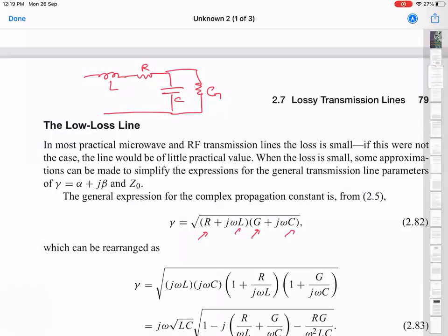The second is that the material you can use for such cables also cannot be a very good conductor. Now, you know about the Wiedemann-Franz law that thermal conductivity and electrical conductivity go together. So if you want a low loss line, then it has to be made out of a material which is a good conductor of electricity. And consequently, it will also be a good conductor of heat.